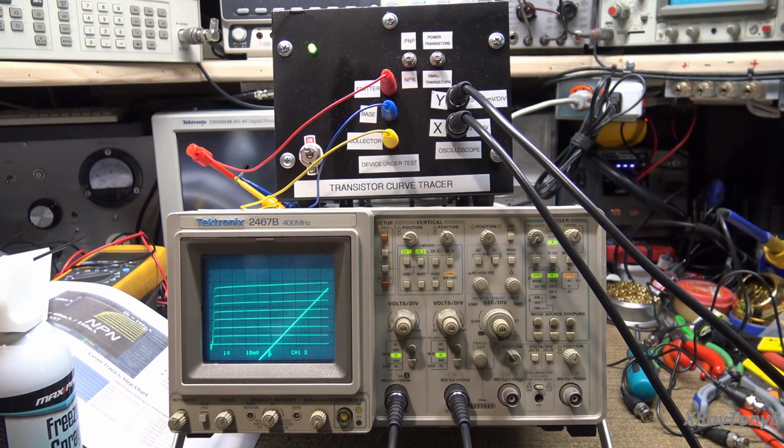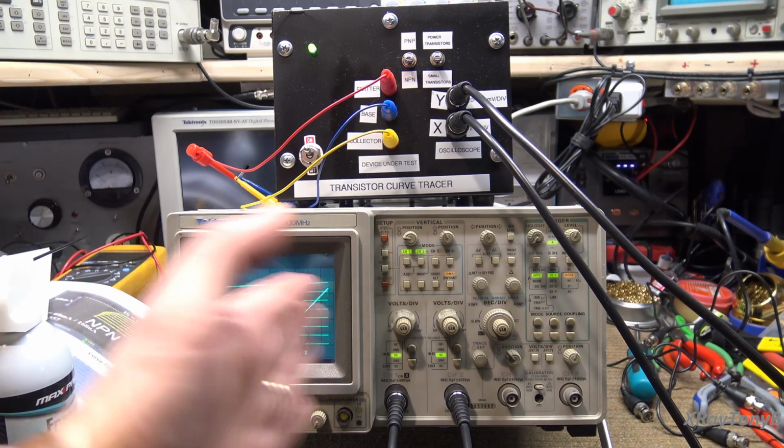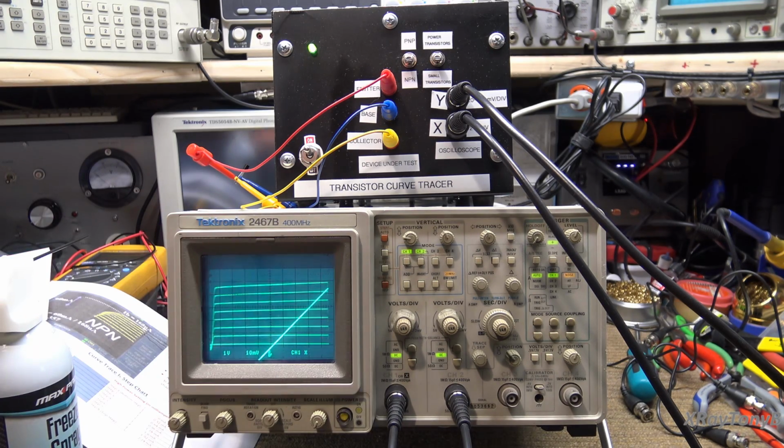Okay, one last thing I feel like I should bring up before we close out this video is a third characteristic. So we looked at temperature, how temperature affects the gain of the transistor and the performance of it. We looked at the early effect and how that affects the gain of the transistor based on the VCE. And one last thing I wanted to mention is the FT, or transition frequency of the transistor.